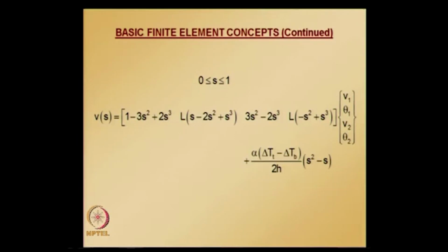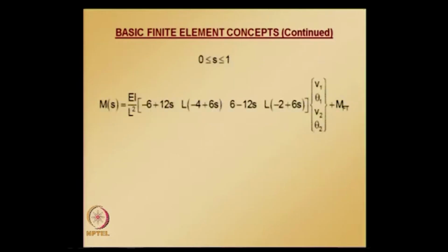And now moments: similarly, a correction term is there in addition to the finite element interpolated values. And please note that there is no shear because of these thermal stresses and fixed end condition, so there is no correction term for shear force.